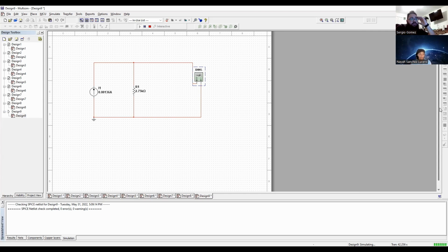The benefit of using Thevenin and Norton equivalent circuits is that we can use a very simplified voltage and resistor in series, or amperage and resistor in parallel, to represent a much more complex circuit that is easier to model for analysis purposes. And that's one of the benefits of using this style of circuit development.